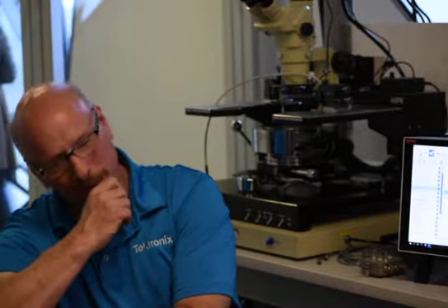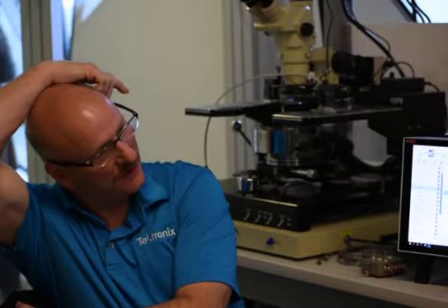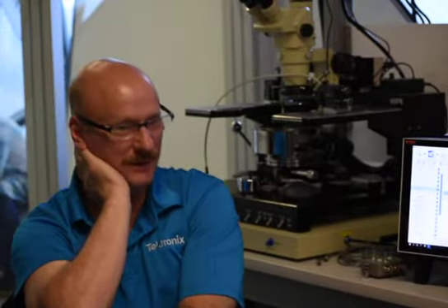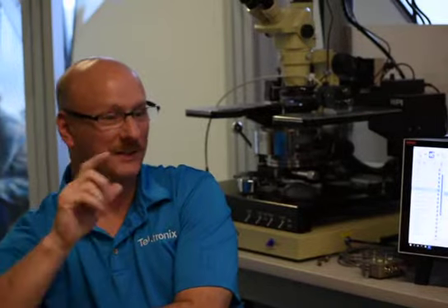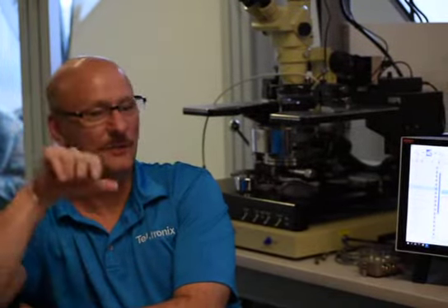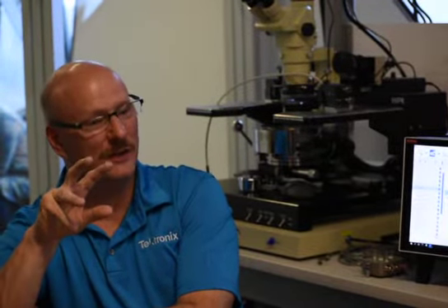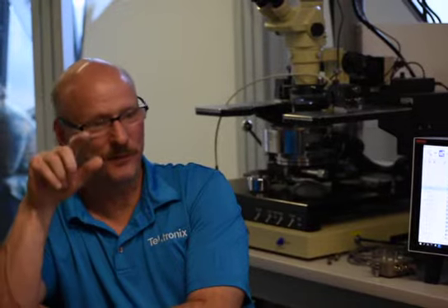Where the pass-through would pay benefits for you is if you're doing any transistor characterization, capacitance, like you want to measure CISS, COSS, CRSS, those parasitics from pin to pin. The CVIV allows you to walk the CV meter around the device. So if you have a 4-terminal FET, including the bulk, there's capacitance between every pin to pin.